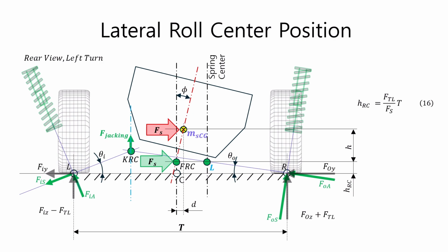The reason why the spring center L is not used as the force roll center is because the displacement d of the center of mass of the sprung mass off the central longitudinal plane must be calculated to calculate the moment that the weight of the sprung mass generates about the roll center. The force roll center must be located such that a transverse force acting on the force roll center does not cause rotational motion in the spring center and must satisfy equation 16.